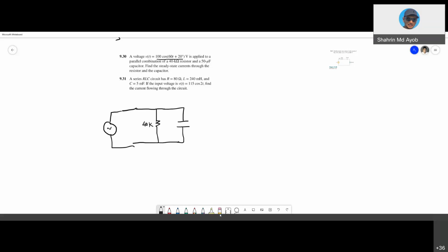But for the capacitor, you need to calculate what we call reactance. So X is reactance. What is X? For a capacitor, Xc is negative j 1 over omega C. Sometimes you will also see on YouTube videos that Xc is 1 over j omega C. But please don't be confused, because j here is at the bottom part.